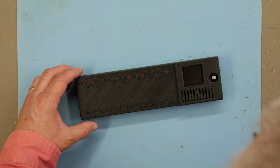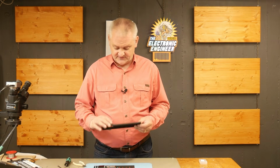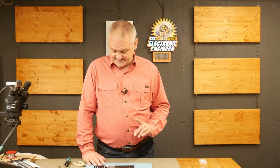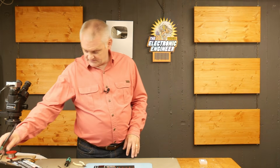I think this is going to work out just fine. Okay, so I placed all the LEDs on the PCB and I checked the distance towards the lid to see they have the right height for mounting. And now I'm just going to solder one wire of each LED, so I can still adjust the placement a bit later if needed.